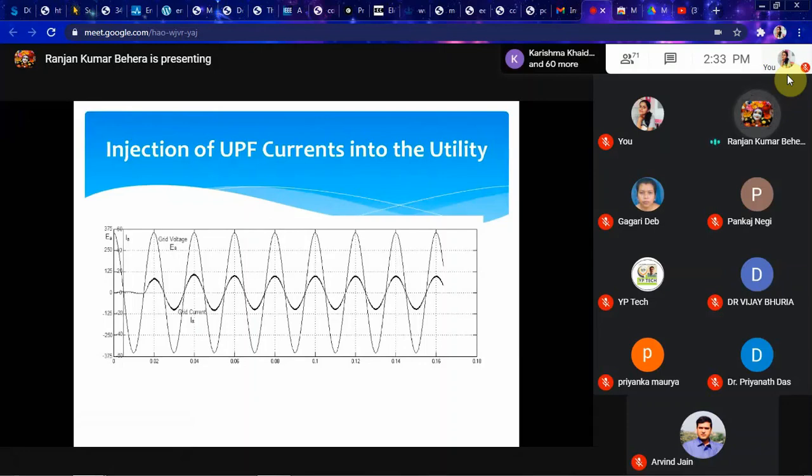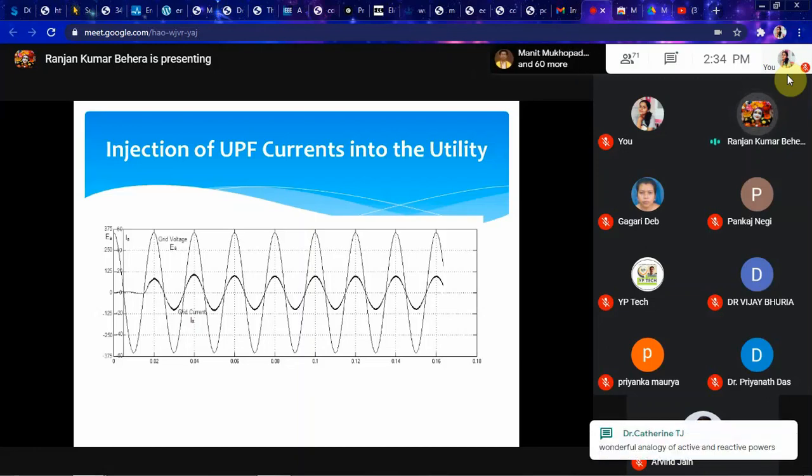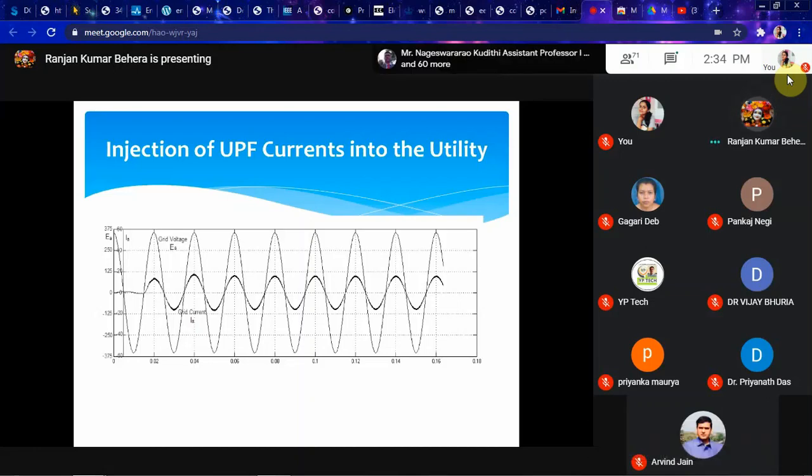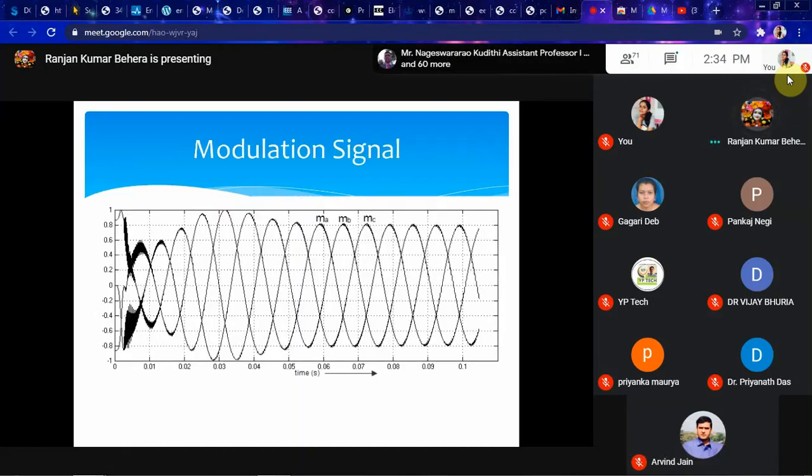That is why inherently the lines have reactive power. But here in this converter, you operate at unity power factor. So reactive power is nearly 0, because VI into cos phi, where cos phi is equal to 1 and sin phi is equal to 0. That is how reactive power is always 0 in a utility friendly converter.